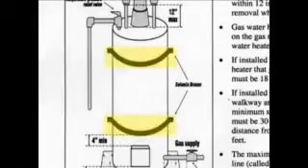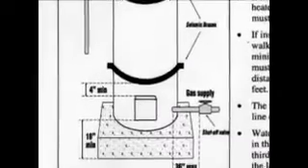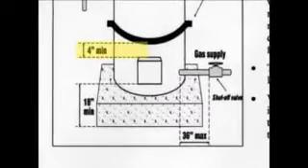Page 28, next page, we're going to be talking about water heaters. There's a fair amount of information on this page here about water heaters. I'm going to have you read it on your own. But let's take a quick look at the diagram. And this diagram is a good summary of what's on this page here. Let's start with the seismic braces. Seismic braces, approximately 1/3 from the top, 1/3 from the bottom. Note the minimum inches of space you need between that bottom brace and the controls, at least 4-inch gap there.